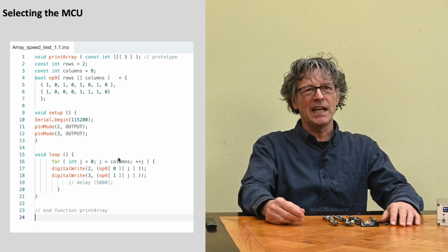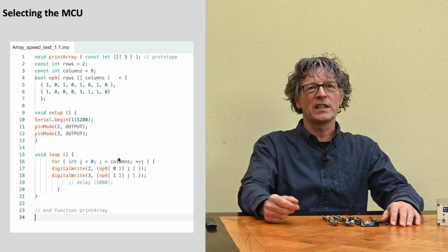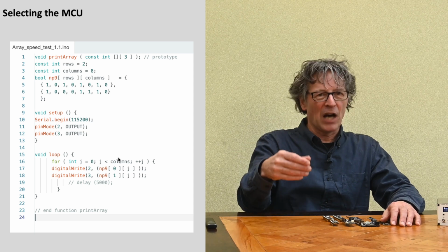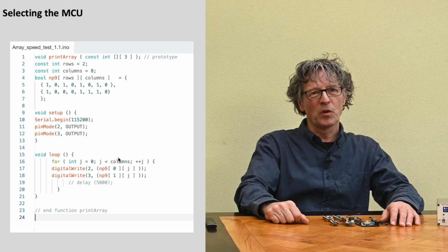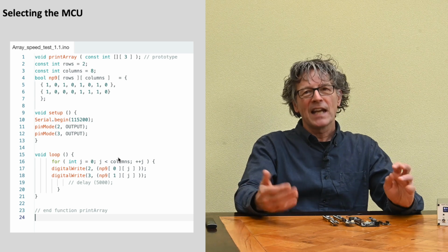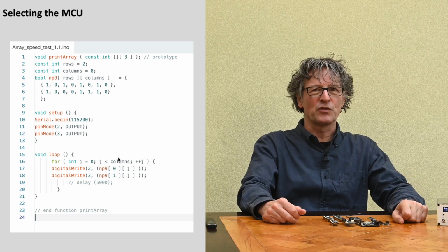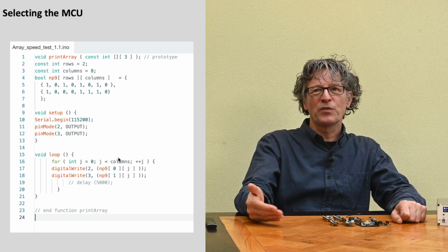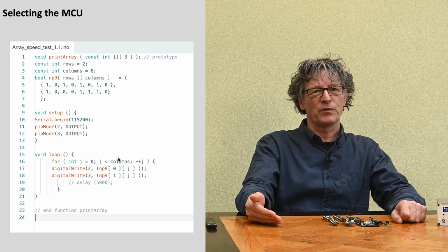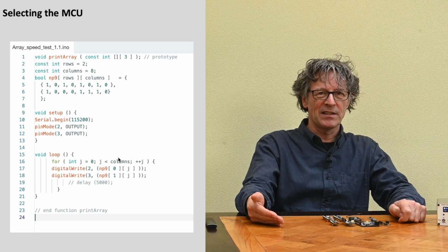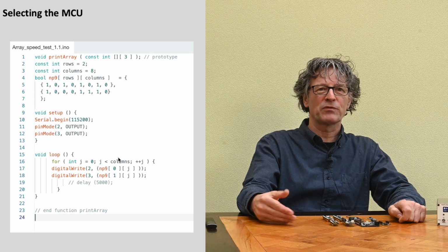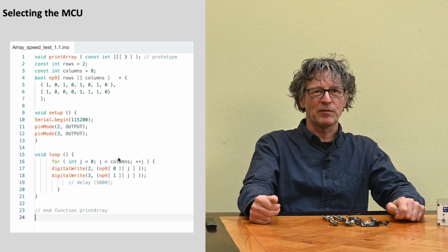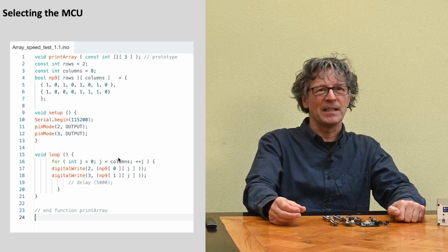I just take 8 different bits, a clock signal and a data type of signal, and I wrote a sketch that takes that bit out of the array, writes it to a digital pin, and then starts again, without any delays. Let's see how fast our different Arduinos or Arduino-likes are in carrying out that code, taking into mind that this is the fastest possible sketch to do such a thing. The real program will be more sophisticated, will write out more things, will have some UI things, so it will always be significantly slower. But this is the maximum rate that we could ideally get in any piece of program there.